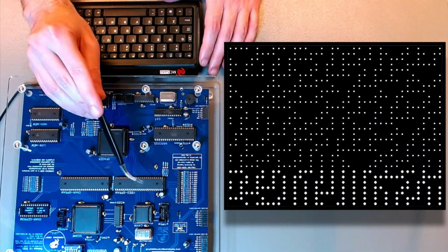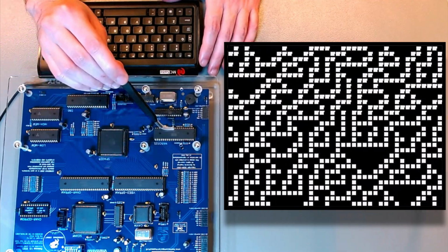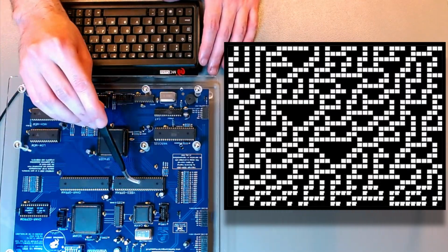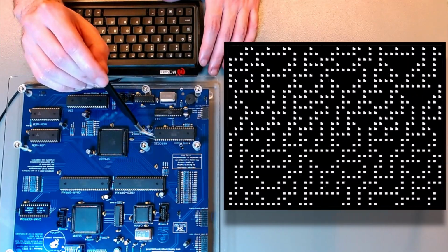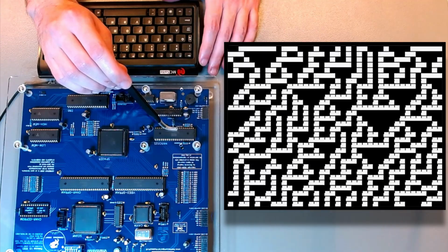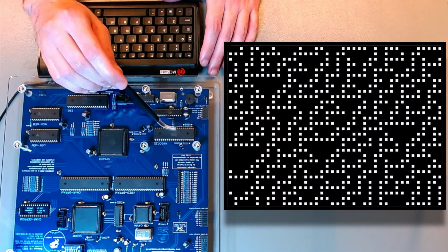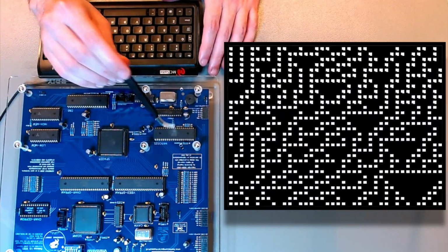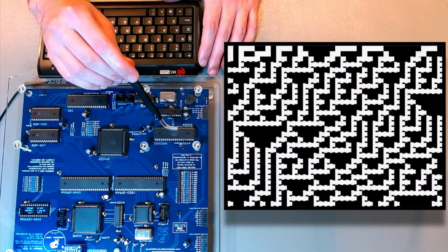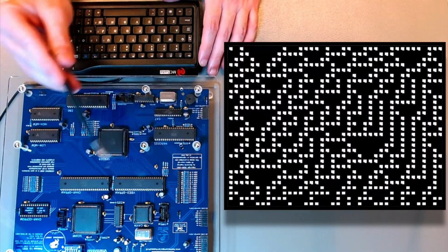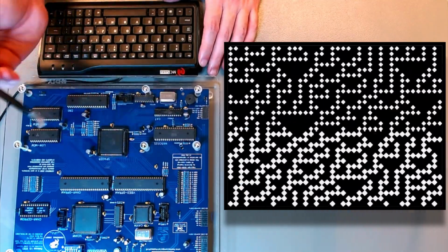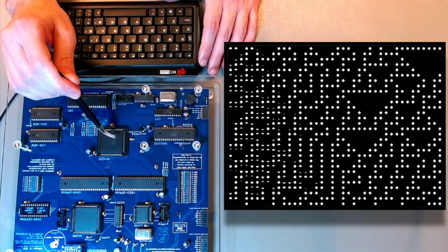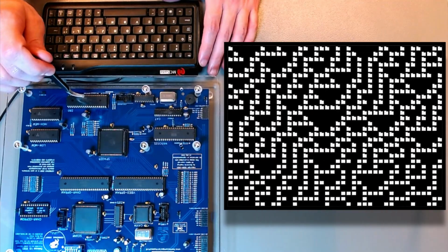These dual-ported memories, sometimes they are busy. If the 6502 is trying to write into the same address that is being read on the other side by the video circuitry, the memory will issue a pause and will force the 6502 to halt for a little while. But halting the 6502 requires this specific timing protocol. You cannot halt it, or you cannot tri-state its buses, before it's already halted for at least half a clock cycle, and you cannot unhalt it less than a clock cycle after you have halted it. So there's all kinds of things that need to be done here, and which for the Z80 are done in die. So it's a lot faster.